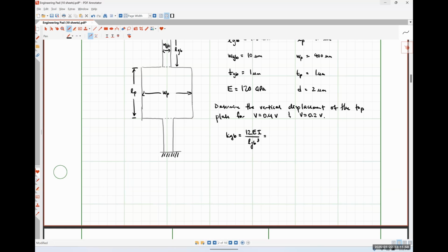So I, in this case, we have a rectangular cross-sectional area. So that should be AB cubed over 12, right? I believe we've talked about that before, and I think you're literally using it in one of the homework assignments, or probably several of the homework assignments. So the factor of 12 is going to wind up canceling each other out. Let me just make a note over here.